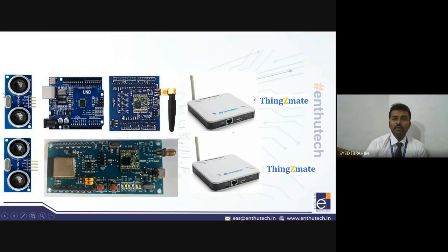to the cloud? It is through this gateway and this LoRa unit. The processed signal is modulated over here and transferred to the gateway. The gateway simply sends the signal to the cloud. Also, from the cloud, we can send a command back to this device, whether we want to operate this device or something. So this is really useful in the case of UAVs.